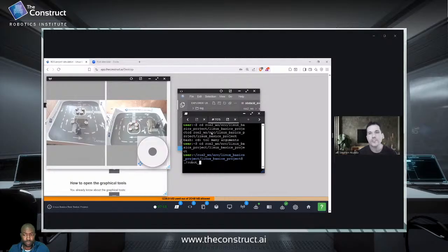If one laser is reading a greater distance than the other, the robot will turn in the direction that has the greater reading, since it's not showing an obstruction as close as the laser with the lesser reading.